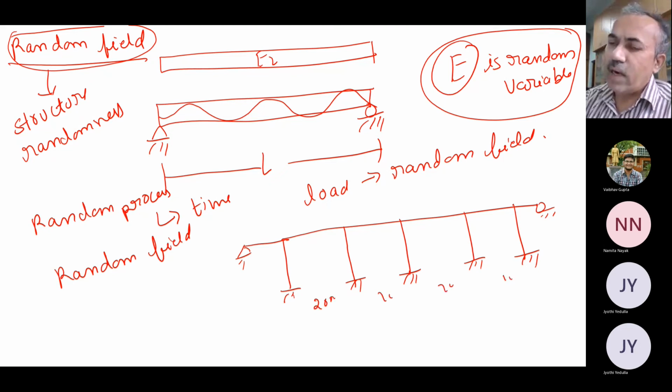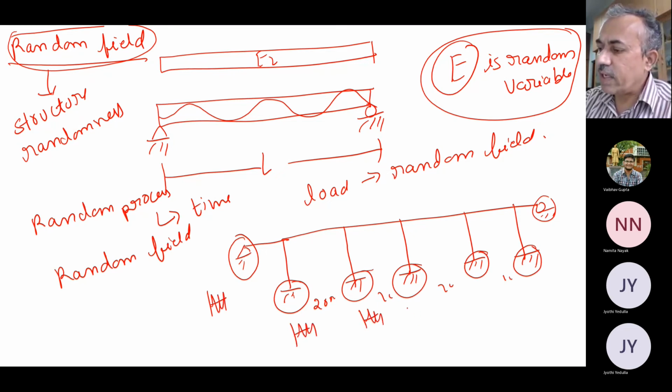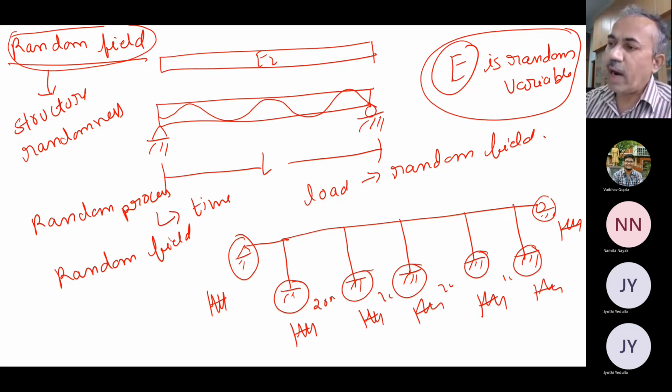Whenever an earthquake occurs, what happens to the ground motion or the accelerations at all these points? It will be random only. If I see the ground motion here and then at this pier, and I instrument here, what will you observe? Will they show any pattern, or will they be completely different?